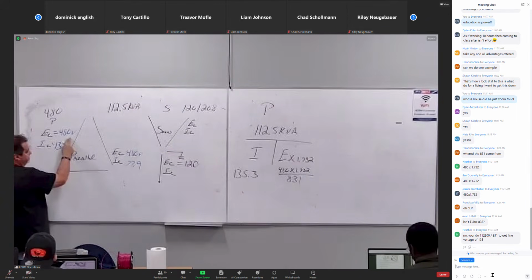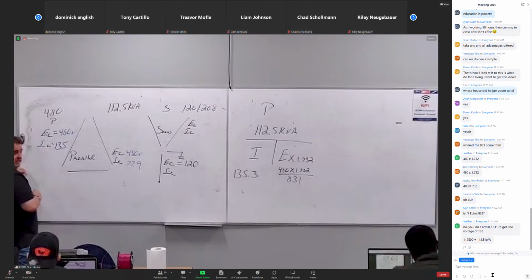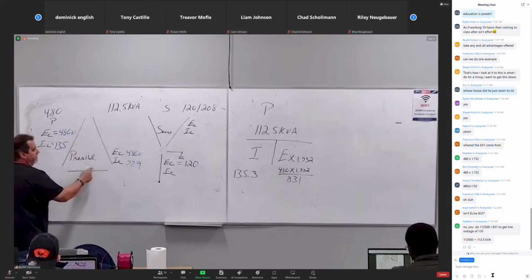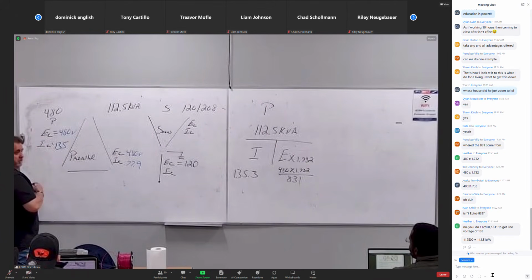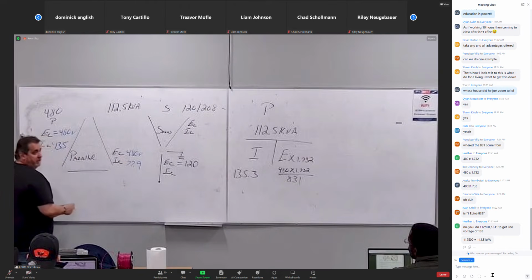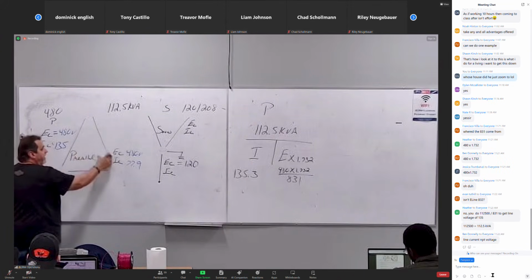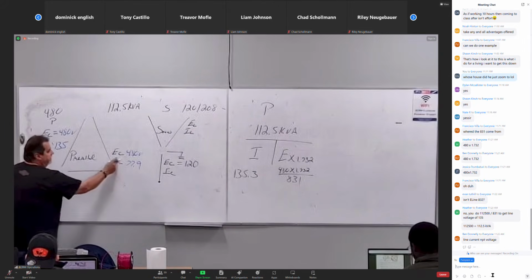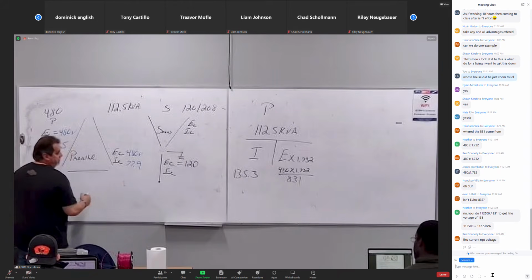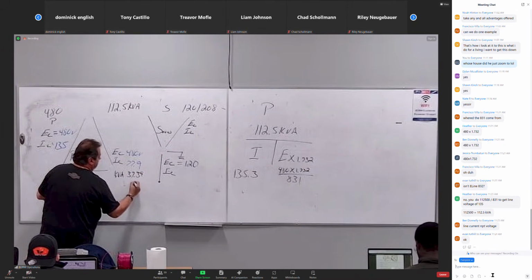Okay? So this goes back to single phase, right? Because it's a coil. It's part of a three-phase system, but this is a coil. Can I solve for power right here? Yes, I can, right? Don't I have E? Don't I have I? It's not three-phase E, it's only the coil, it's single phase. So I'm gonna take E times I. What do I get? 37,392.